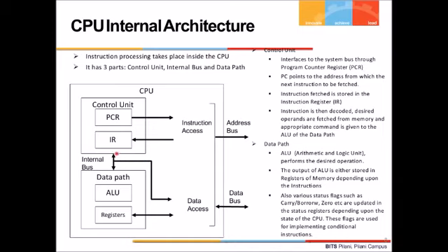That's why here we are accessing the instruction memory, remember. But after the instruction is decoded, we have to access the data memory, right? So we are sending the data address here. The data address goes out through the address bus, then the data comes through the data bus. Okay. Now the data came. If it is a memory access and memory read, the data comes and it is used. Now say it is a memory write. What will happen? The output has to be written to the memory. So the data will go out. That's why the data bus is bidirectional.